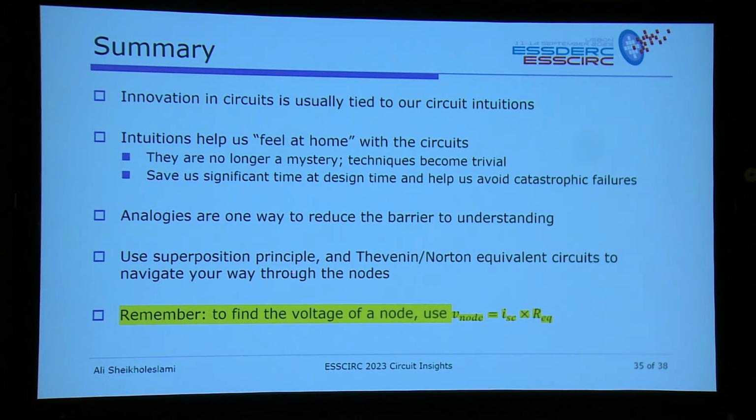Use the superposition principle, Thevenin and Norton equivalent circuits to navigate your way through the node. And I think the last one that I want you to remember from this talk is: short circuit a node, measure the current, and multiply by equivalent resistance.